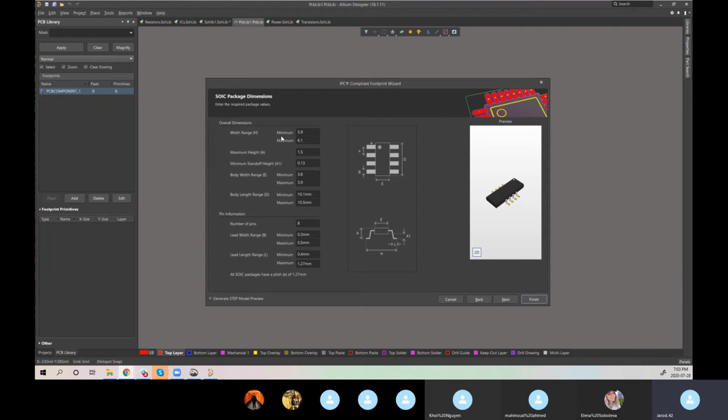And since we properly put in what the height and the width is of the packaging, this would actually be okay because the pads are where they're supposed to be. But the model looks ridiculous because it's overhanging a lot. But technically, this going this far would actually make it an okay part pad-wise, but it is just ridiculous.